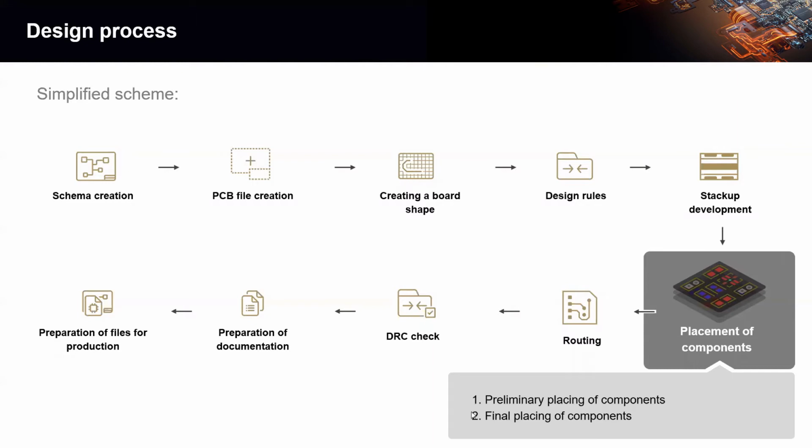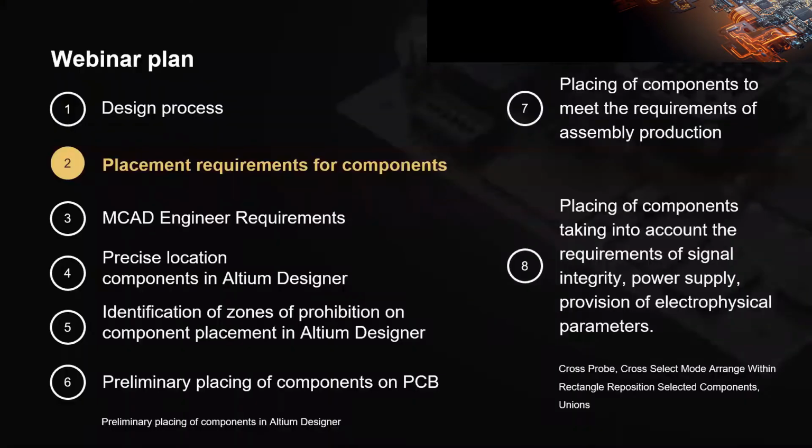Okay, and eventually, of course, there are later steps in the design cycle for routing, doing a final design rules check, preparing all of your output files, and then preparing those files for production for your bare board for fabrication and your assembly files, okay?